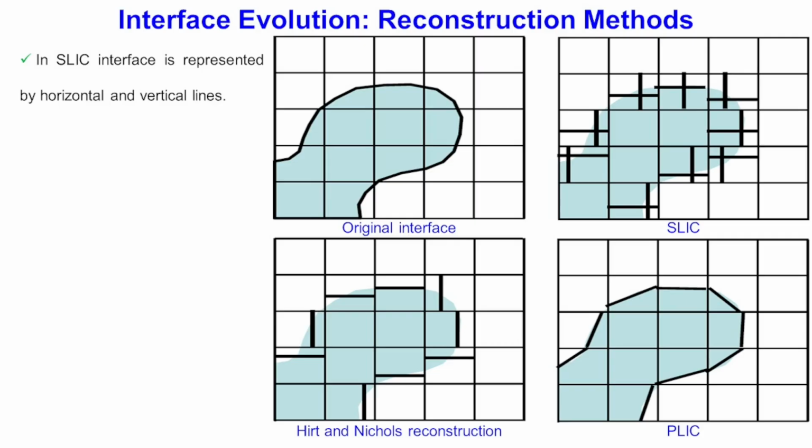So it means that in the volume of fluid method, in each time step we do two additional things. One is we do the interface reconstruction based on the volume fraction data, and then in the next step we advect the volume fraction field to the cells for the next time step, and again then we do the reconstruction. Is this point clear?